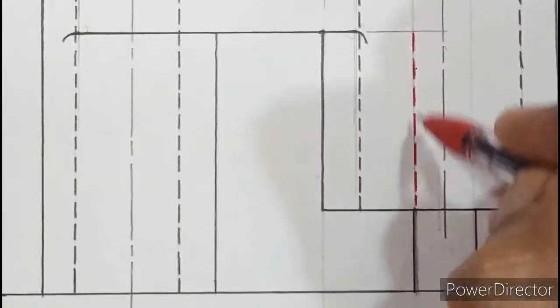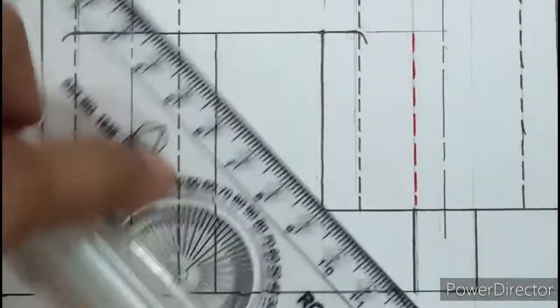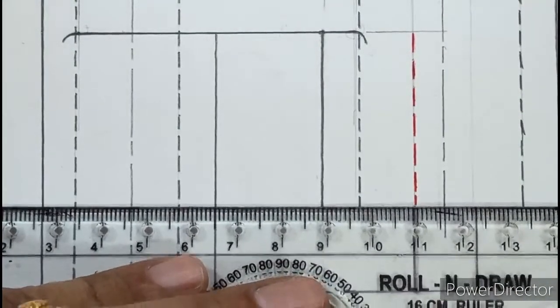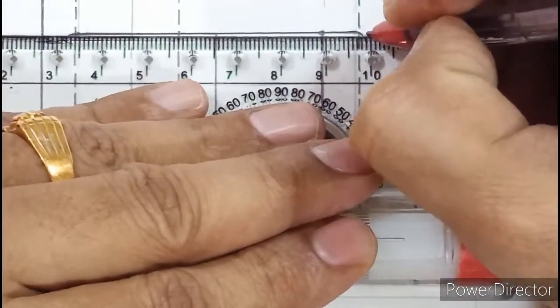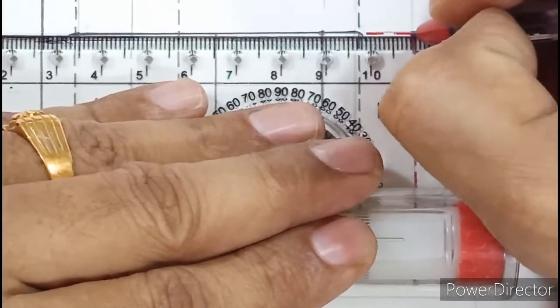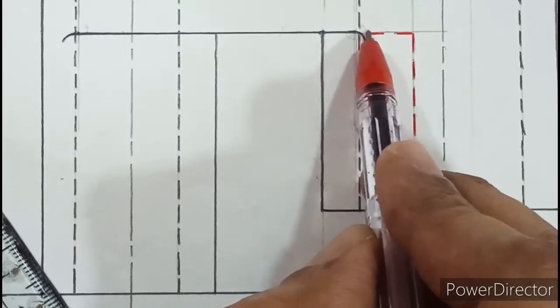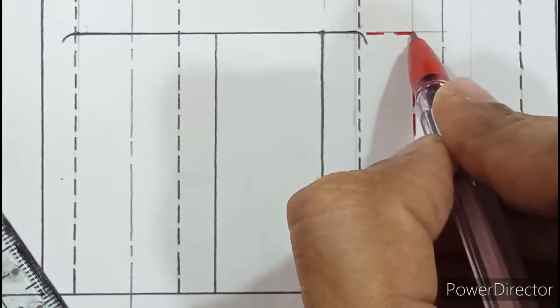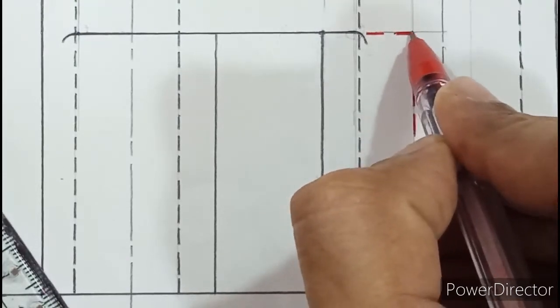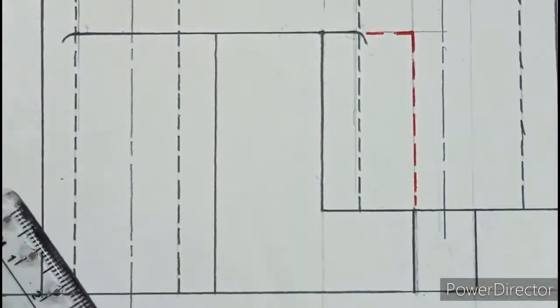So this edge what has gone inside by red color, that is this edge. Now you need to take an L-shaped turn. From here if you align the scale and move up, from the curved part leaving a gap of 2 mm, you need to take an L-shaped turn. Now see once again the dark line and the hidden line are in continuation, so here you need to leave space. And whenever two hidden lines meet, the corner should form L shape. So that is why this L shape has to be here. You have to make a proper L shape here and you need to leave space on this side.